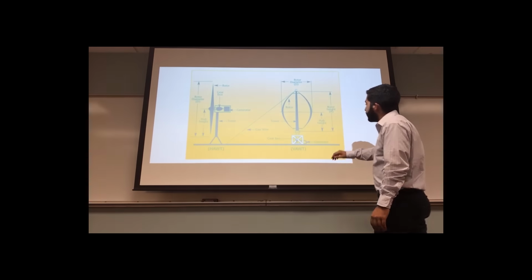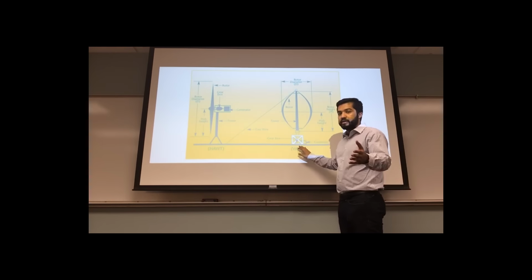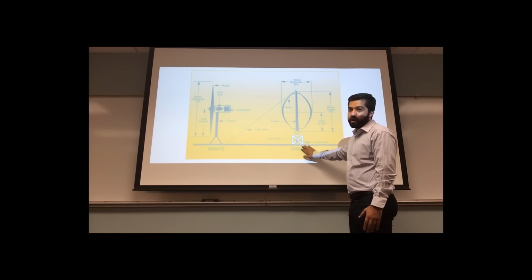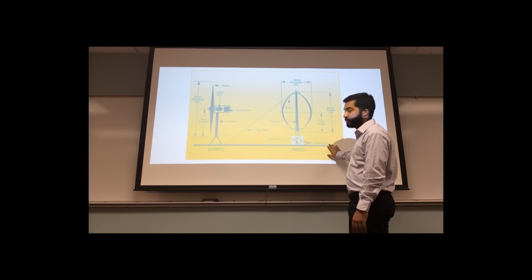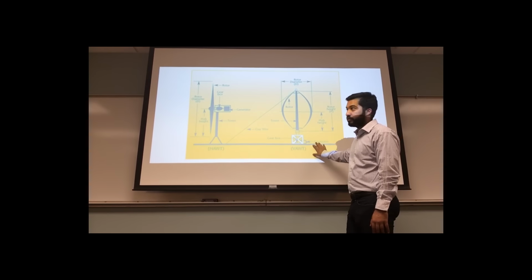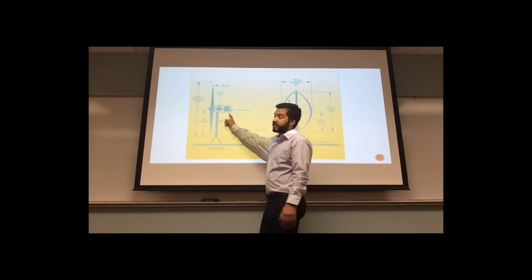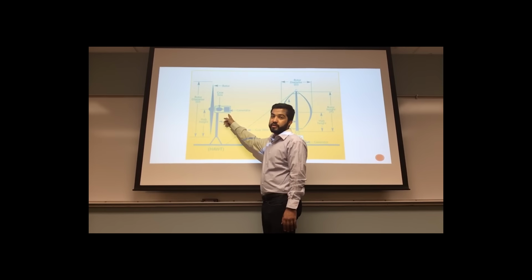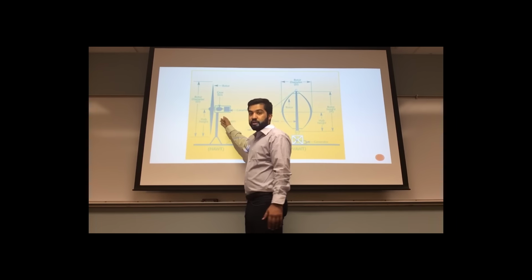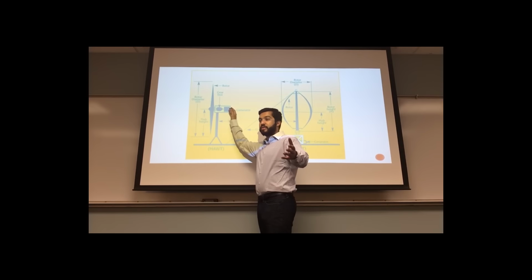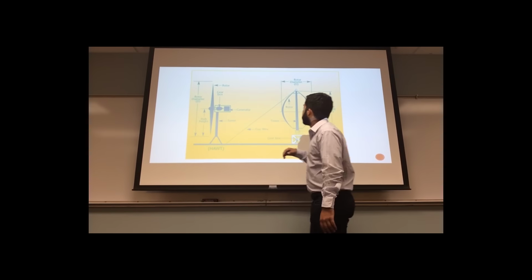And these are the major parts. As we see here, when you're doing maintenance, especially for a vertical axis, the generator, gearbox, and all that assembly is here, and it's easier to get to. In a horizontal axis one, it's all the way up here on the tower. So you would have to either get a crane or all these other things, in hundreds of meters in some cases.